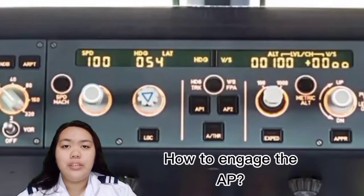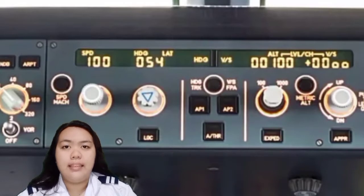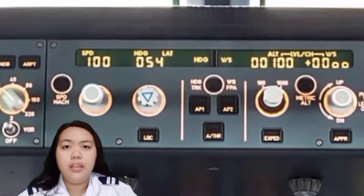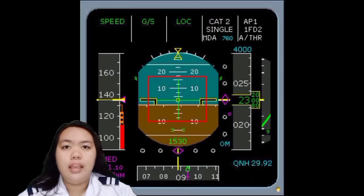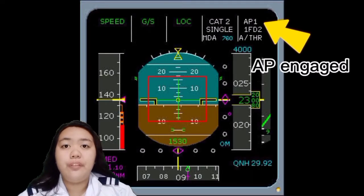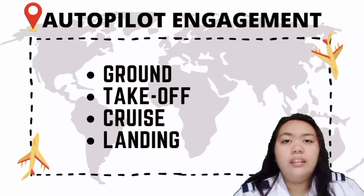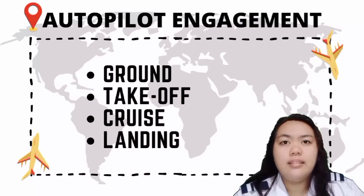How do we engage the autopilot? The autopilot is engaged by pushing the designated button on the FCU. To monitor, an indication is displayed on the top right of the PFD, or the primary flight display, to confirm that the autopilot is indeed engaged. The autopilot can be engaged while the aircraft is on the ground and both engines are shut down for maintenance purposes. If any of the engines are started, the autopilot disengages.